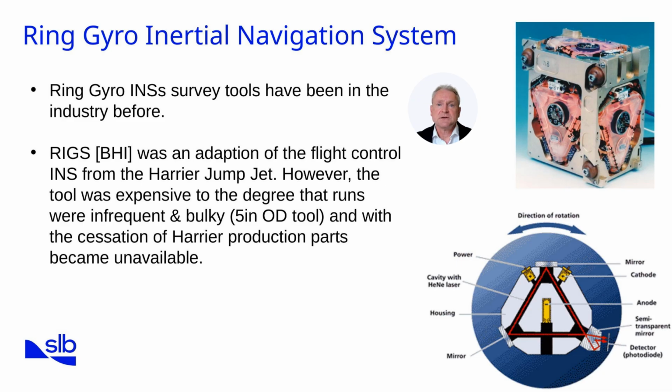Ring laser gyros are a form of optical rotation sensor and, unlike the preceding mechanical rotor systems, contain no moving parts in their simplest form. Within the sensor, which contains a machined quartz block, 2 laser beams are formed, one moving clockwise and the other counterclockwise, around an enclosed polygonal optical path loop with 3, 4, or more sides and mirrors at the vertices. These laser beams interfere with each other, creating a standing wave diffraction pattern observed by a photodetector located at one of the vertex mirrors.